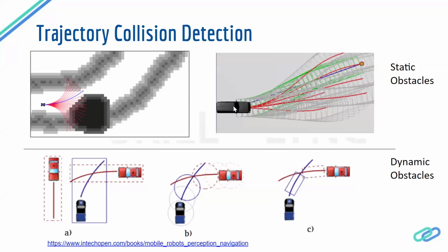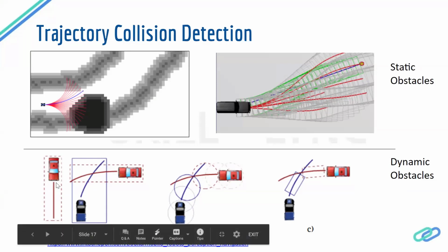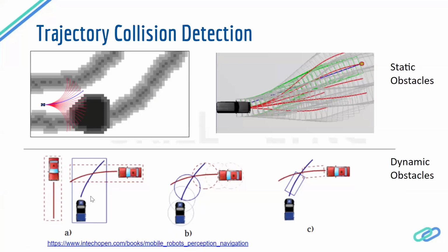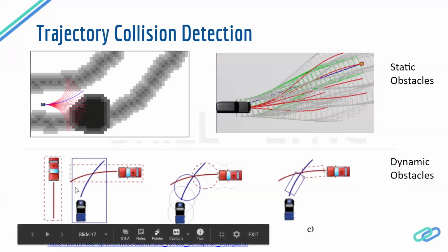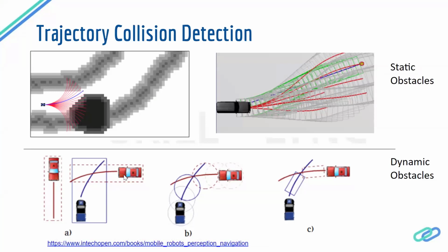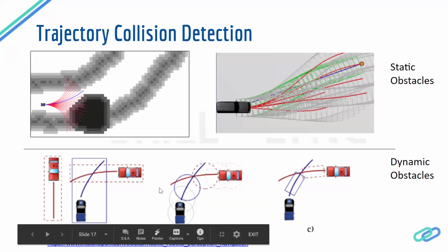And the next one is the collision detection in the dynamic environments. This is a bit more tricky because we also need to see in time where the other objects will be in future. Here you can see that, let's say, for the next 2 seconds, this is the trajectory of the car, this is the trajectory of the red car and another red car. If we draw a box around it, we know that in the next 2 seconds, the paths of these two cars are not intersecting. And for the right side, the bottom car and the right side car, we see that the trajectories are intersecting. Now we can do something like the forwarding, but in time, not in space.